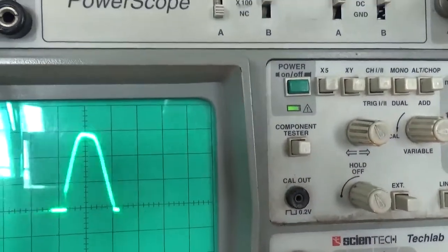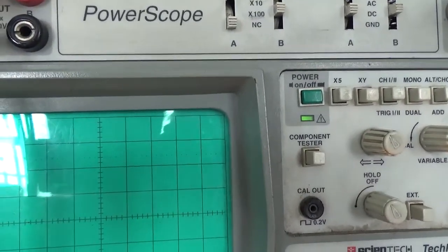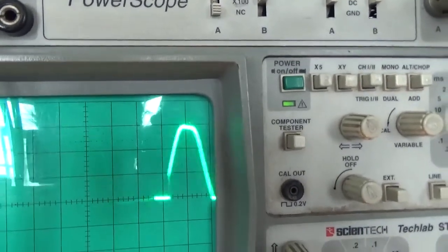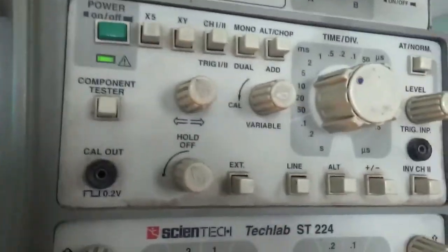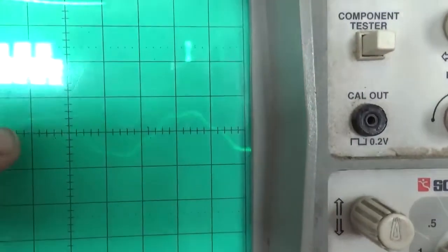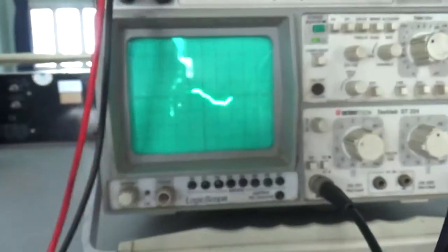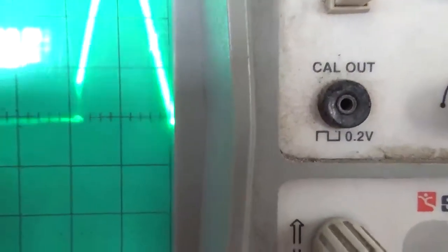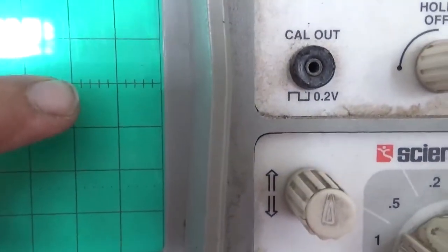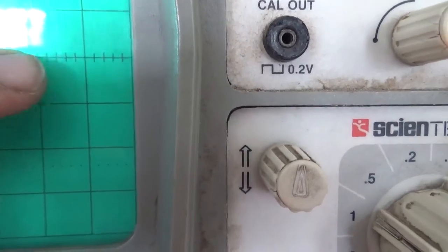So now I am setting alpha. I am varying the resistance knob and setting alpha to 18 degrees. You can observe this 0 portion here; this is the starting point of alpha, the starting point of the positive half cycle, and the 0 voltage appears till the first point.